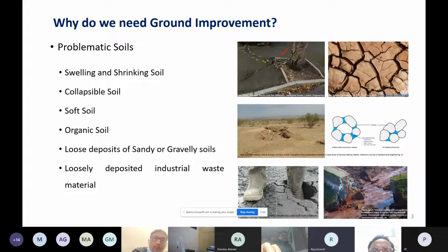Due to this swelling phenomenon, the pavement that was overlying this swelling soil underwent distresses. The opposite happens in the summers, when the water dries up. At that time, when it tries shrinking, because again it had occupied a 700% increase in volume, there can be a lot of cracks in this kind of soil. So this can be a problematic soil to work with.